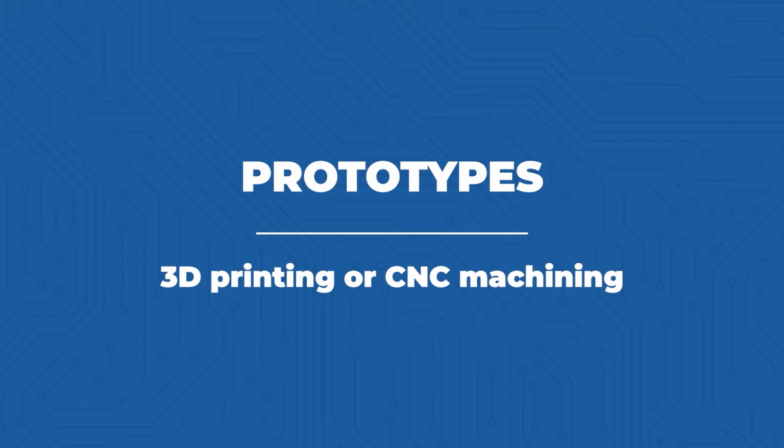3D printing is the most common of those two methods used for prototyping, but CNC machining has some advantages in that it allows you to use a production plastic. You could basically buy a block of plastic that would be identical to the plastic that you use in production, versus 3D printing, which uses prototyping resins designed to emulate production plastic, but they are quite a bit different.